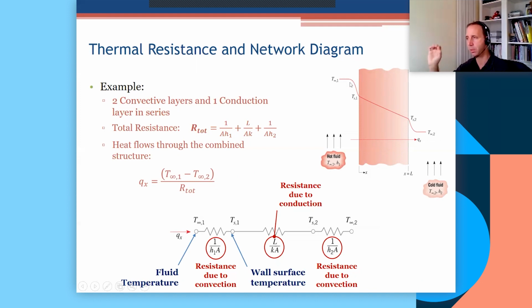If you had zero resistance to heat transfer, then even with heat transfer taking place, the temperature would be the same across the points. That's physically impossible, while it is possible, it's extremely unusual. You get a temperature difference because you've got a resistance to heat transfer. You need the temperature difference to drive heat flow, but the reason for the temperature difference is the existence of a resistance to heat transfer.